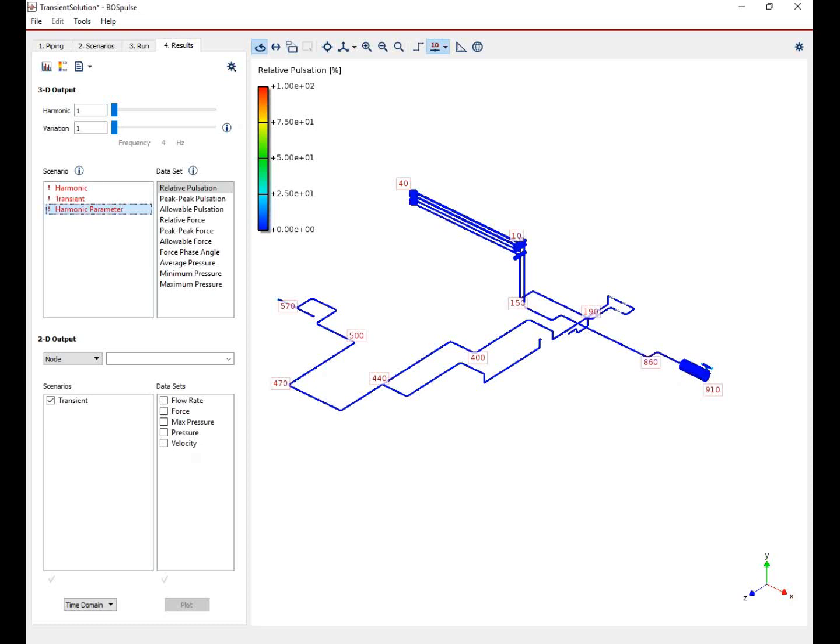So vibrations are most often initially caused by acoustic resonance. If there's a wave standing in your system which is exactly excited, you can change the RPM of your compressor, for example. Even if the gas properties change a little bit, you can already move away from the acoustical resonance and the shaking will become less.